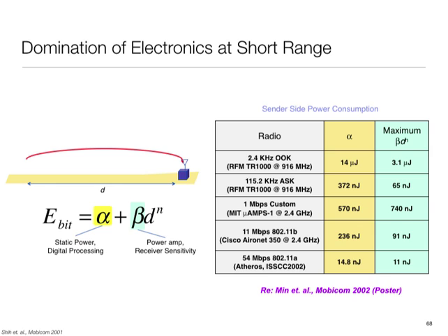And in the case of radio, two different things: the energy because of sending the RF signal over a certain distance, which is the distance dependent term, and the energy consumed by the electronics, and how roughly speaking the range for which a radio is designed has an impact. Generally speaking, for short range radios, the relative ratio of receive and transmit energy increases, and in fact can become greater than 1, and that takes you into a territory where certain things which made sense for long range radios no longer make sense.